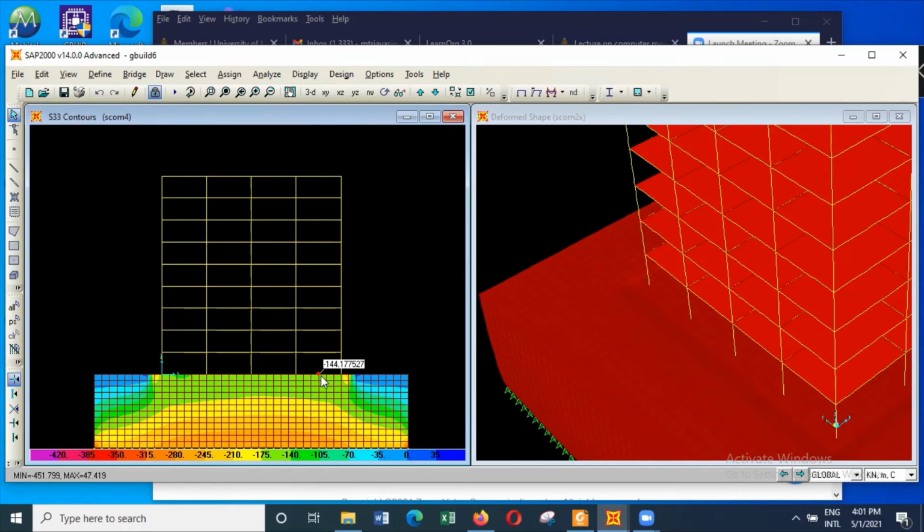And you can see the earlier problem also, with the sandy soil, we got similar answers. Soil pressure of about 140. This one also we are getting similar answers, but we are getting the variation of the stresses in the soil, and you can see how the soil will distribute the stresses with the height and also laterally. You can see how the soil will disperse the pressures laterally. And in addition to that, any questions on this?